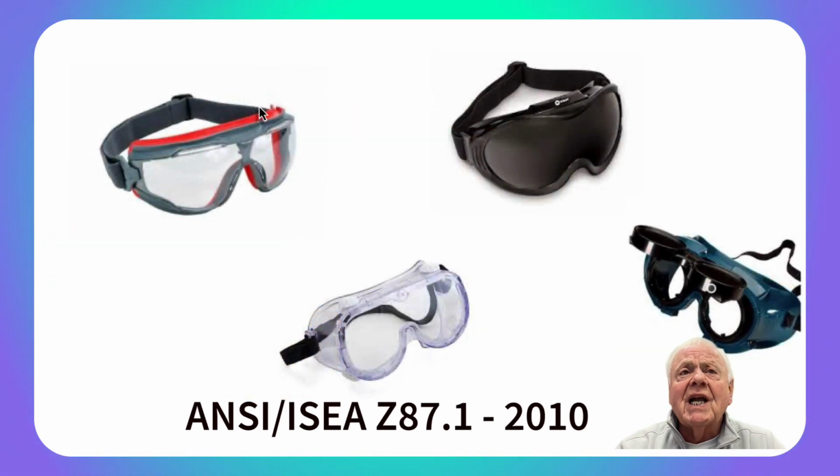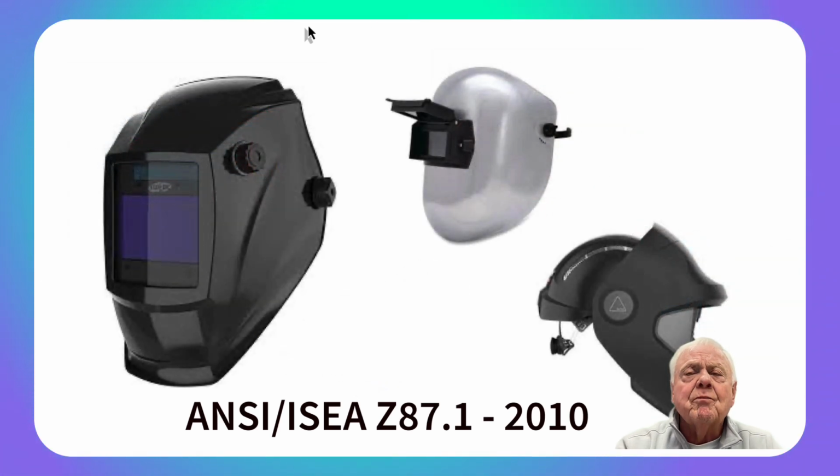Then we move over to goggles. Goggles give you the same type of protection, but they're usually tight-fitting, which will give you more peripheral protection. Some are chemical splash, some are just intended for different kinds of sharp objects or materials being thrown around. And then there are the kinds that have lenses that are tinted for various jobs like cutting or brazing or something like that. We always have to make sure in those cases that we get the appropriate lens shade. We'll talk more about that in just a minute.